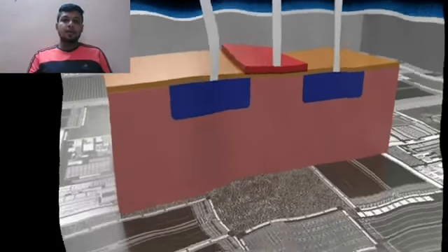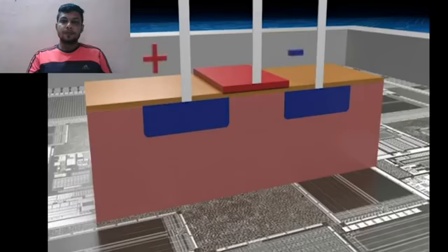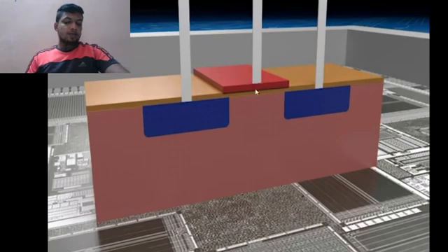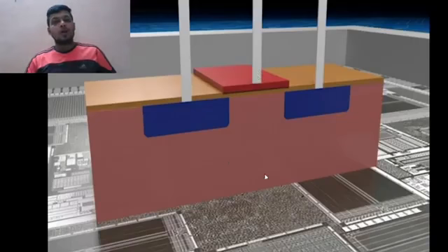They also have an additional layer. Here you can see silicon dioxide, which acts as an insulator, and a layer of electronically conductive polysilicon is applied on top of this. Every transistor has three terminals. This is the gate terminal. This will change according to which substance is used. The two other terminals are the source and drain.